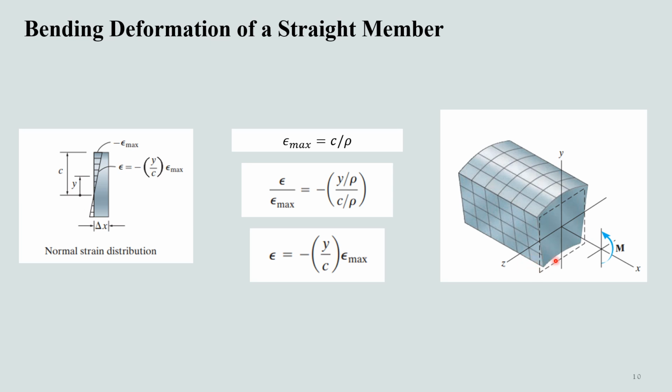Such deformation will cause the cross-sectional dimensions to become smaller below the neutral axis, and above the neutral axis the dimensions will actually become larger. For example, if the beam has a square cross section, it will deform in this shape, but these effects are secondary and negligible. Thus, we do not consider these effects in the normal derivation of the flexural formula.